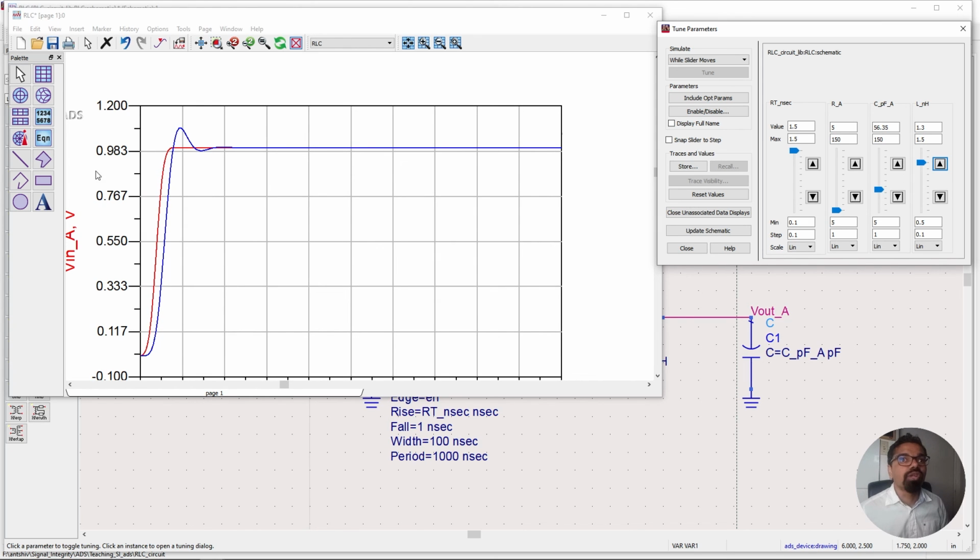So that means there is a correlation between the rise time, the peak of the oscillation, and the swing. And this is important when we're looking at ringing and doing some TDR analysis reflections. You'll realize that this overshoot and this undershoot is very dependent on the rise time. So when we're doing signal integrity and analyzing our circuit, it's very important to understand the rise time, because the rise time can cause a lot of this ringing, and a lot of the parameters based on signal integrity is based on rise time.